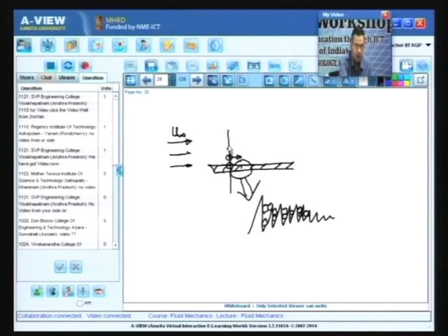As you go further away from the wall, you will find that the velocity is even more, but it is still not u infinity till you come to a location where the velocity is almost 99% of u infinity, for all practical purposes. So, you can see that a velocity profile develops till that location, and beyond that the velocity is more or less uniform.